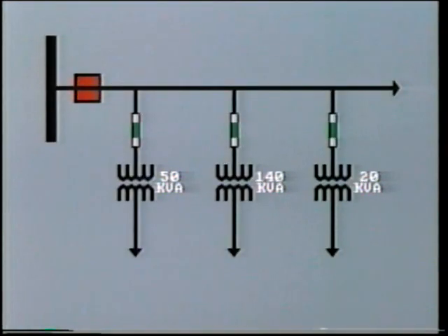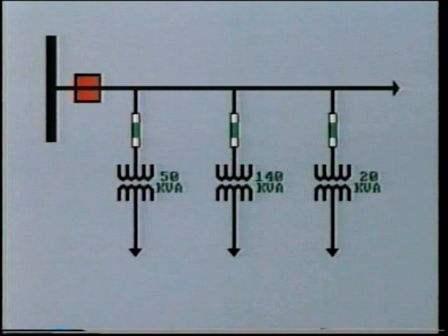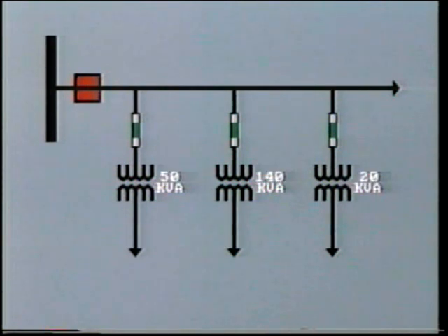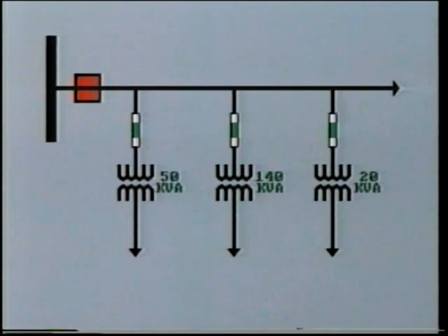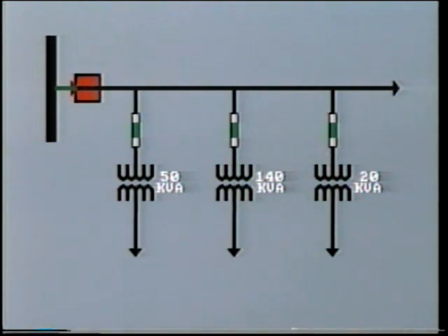On smaller transformers, it is usual to omit the primary side breaker for economic reasons. Typically, we may have many large and small distribution transformers tapping off a distribution feeder. The feeder will be fed from the substation bus through a breaker. But each distribution transformer will be protected by high-voltage fuses only.